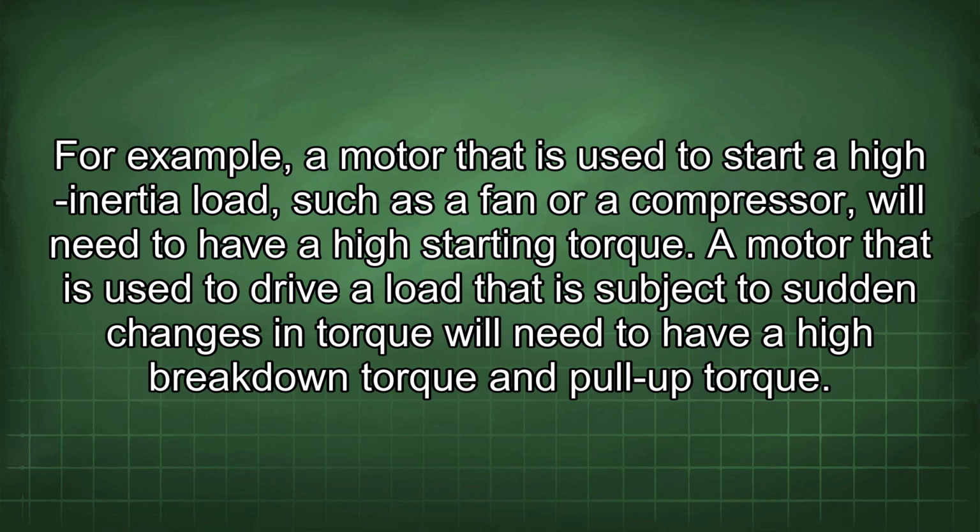For example, a motor that is used to start a high inertial load, such as a fan or a compressor, will need to have a high starting torque. A motor that is used to drive a load that is subject to sudden changes in torque will need to have a high breakdown torque and pull-up torque.